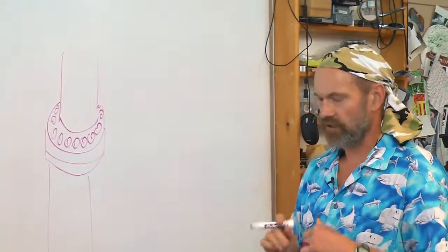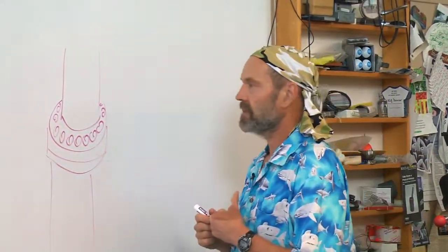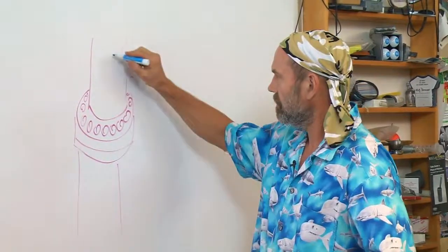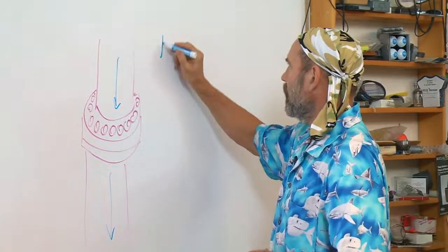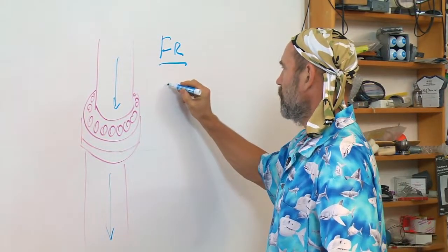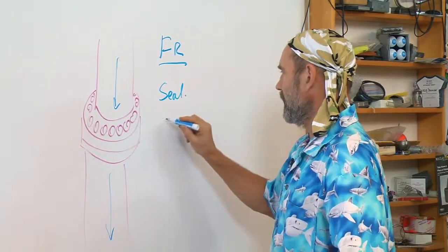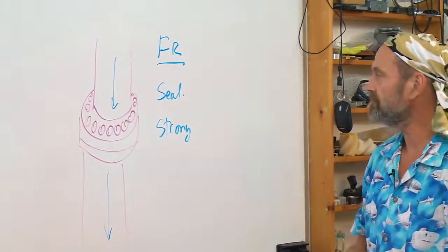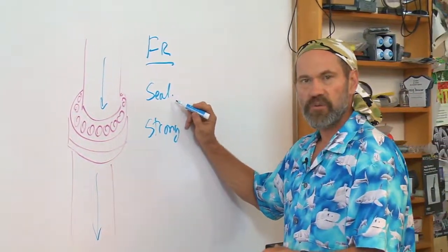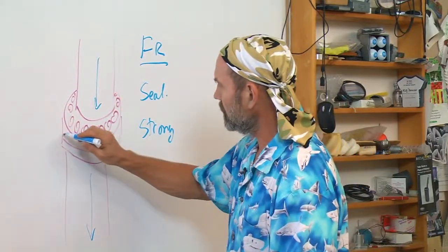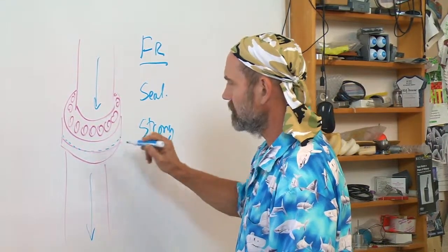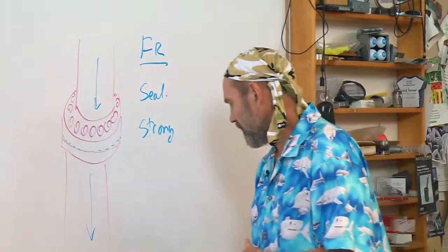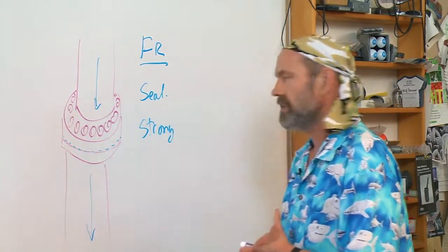This gets back to the function of a joint. In this case, where I've got the flow of a fluid through the joint, the functional requirements are the joint has to seal and it has to be strong. For there to be loads on the pipe, it has to resist that. The bolts themselves will not seal. There'll be some sort of either a gasket or O-ring inside the joint. And even if it was a metal-to-metal joint, which is rare, any kind of seal then relies on even pressure.